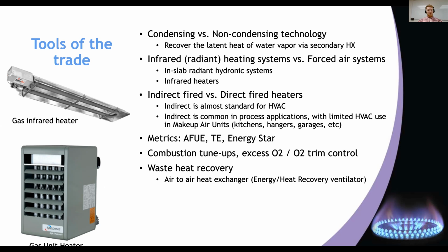And then the waste heat recovery that we talk about with ERVs, energy recovery ventilators, these can also be done with runaround loops or coils. Anywhere that you have heat and you have a useful application for it somewhere else can be a candidate for waste heat recovery. And then it just becomes a question of how difficult is it to move heat from one place to another. And I think the IAC has quite a bit of experience looking at waste heat recovery. But if we go back to the slide a couple ago and talk about those custom applications, which are the largest in terms of quantity of savings, a lot of those custom projects either arise from or are basically waste heat recovery in some form or another.